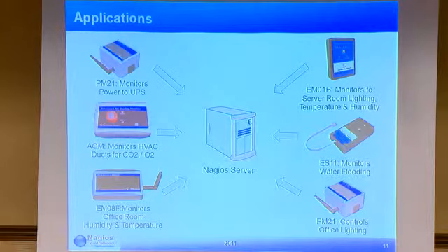And you would be able to set up threshold values in Nagios. If you know that you're going beyond a few hundreds of amperes or so, you would be able to say, okay, if my power goes down, my UPS would not be able to take that load. So you can have such alerts set up. And even if the power to the inlet of the UPS is lost, the power meter will read zero current and zero voltage, and that can give a critical high alert and probably send emails to you too.